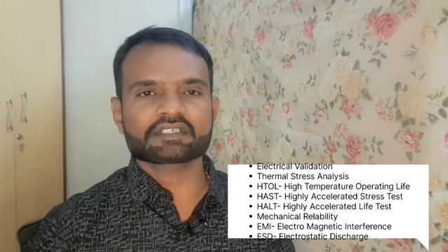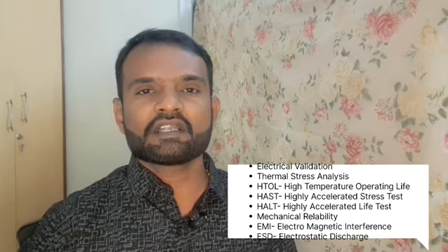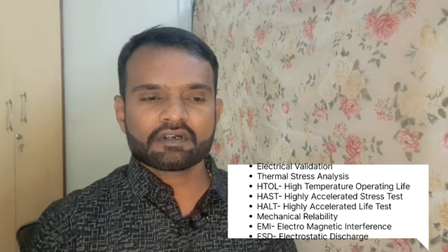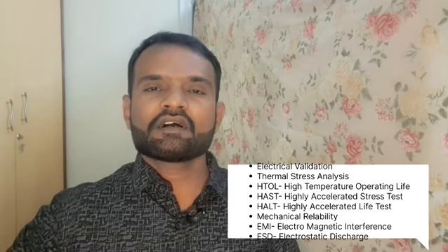So next comes mechanical reliability testing. That is again a stress analysis we do, to see how it is impacting the mechanical components basically. The last one is EMI and ESD testing. EMI is electromagnetic interference and ESD is electrostatic discharge. Any nearby component in the given board, one component can get impacted by this magnetic interference. So basically we need to understand how this creates a problem at a system level. So these are pretty much the testing required when we do the qualification process.